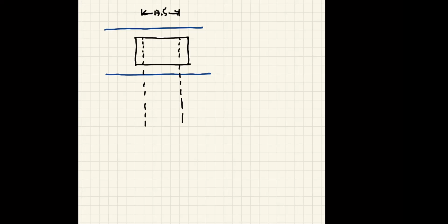And the size of the plate here, that's 20. And remember, I have the n that is equal to 10. Okay, so that's the size of the plate. And I believe that the beam width here is given as 25 centimeters. Okay, so that means you can see that you sort of have the room left here for 15 centimeters, or you can say it is 7.5 centimeters on each side.